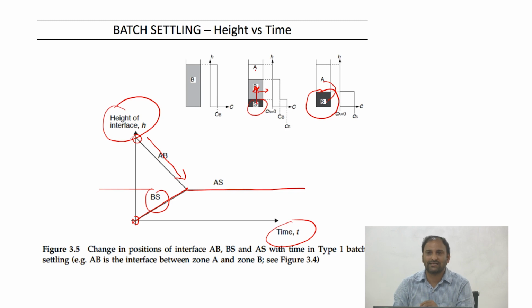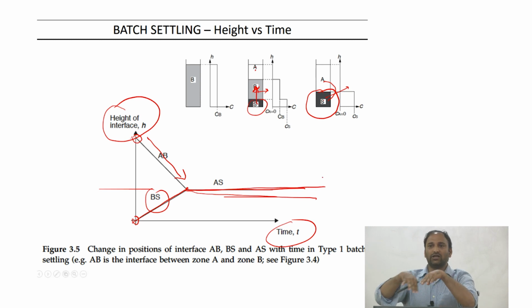Okay, what may happen in some cases is that if there's a compaction, even after the formation of this A and S interface, of course S will have some fluid and the particles as well, right? There's a lot of concentration of particles in the bottom. There'll also be some fluid. Now imagine that you may have a case where the particles form some kind of clusters in the bottom. Now with time you could still evolve. So this AS interface may in practice reduce slowly, however if the particles that are present in S can support their own weight, typically you will see a very constant AS interface, and that's going to remain as a function of time.